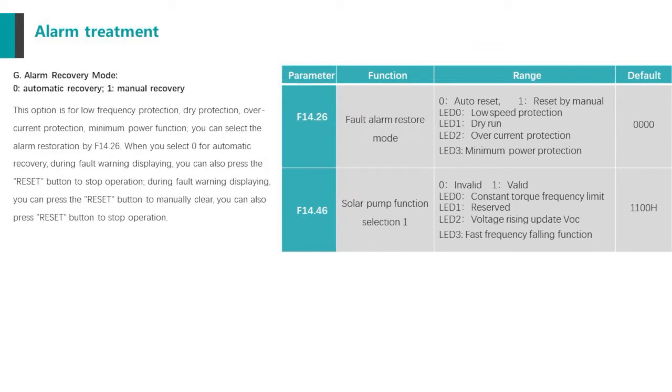But please kindly note that there are two recovery modes. If the recovery mode is selected as manual recovery, the alarm will not disappear automatically, even when the external condition is normal. Of course, the default setting is for automatic reset, that is F14.26.